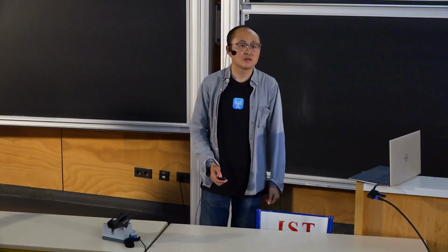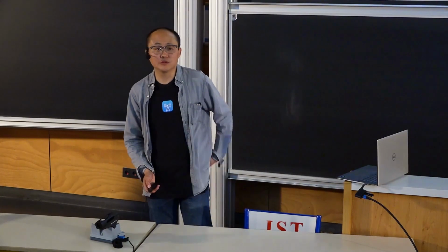Hi. You mentioned that you used Xilinx IPs. Is that used in this digital baseband, or only in the DMA or something like this? And if you use this Xilinx IP, are they free or paid ones? Because I know that Xilinx has some paid libraries. Yeah. For instance, the FFT module. In the transmitter, we use the open source FFT module. In the receiver, we use the Xilinx FFT module.